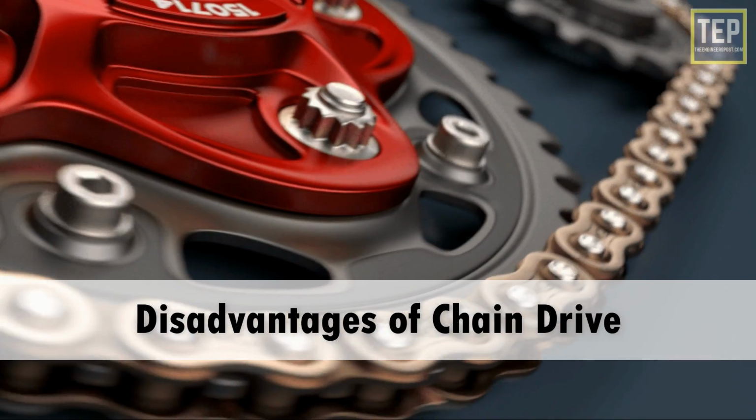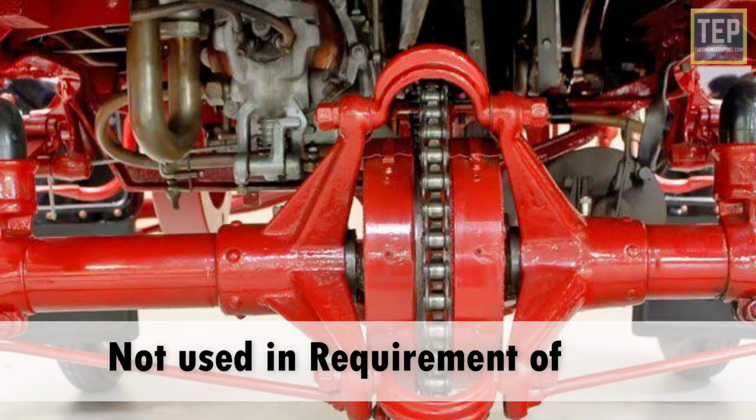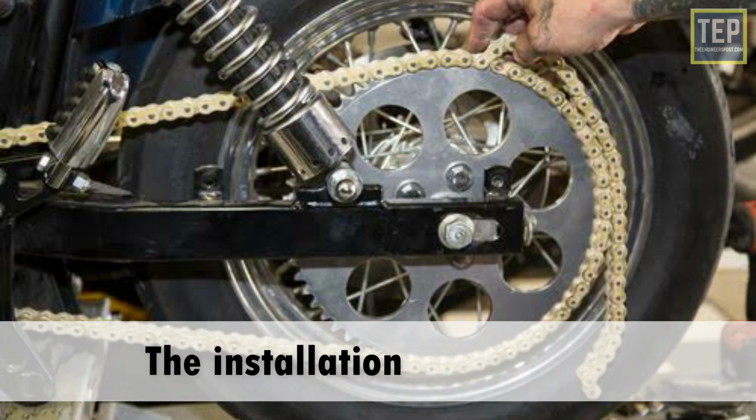Disadvantages of chain drives. The major disadvantage is that they require more and frequent lubrication to avoid rust. They cannot be used where there is a requirement of slip. We can't keep a chain drive in the open; it needs housing or covering. The installation or initial cost is more.